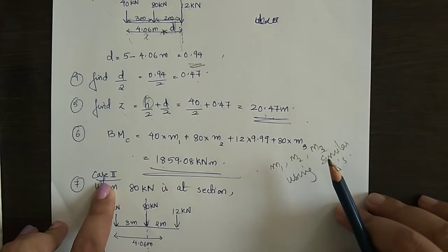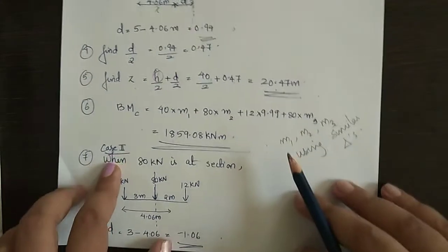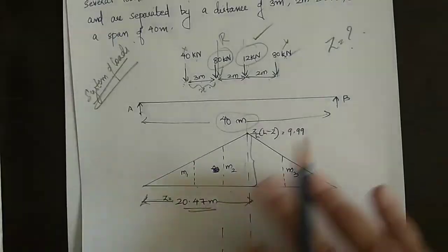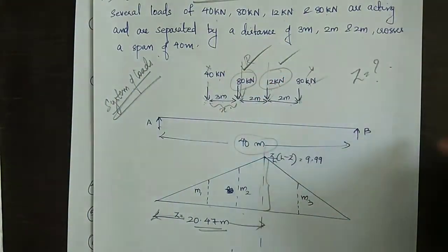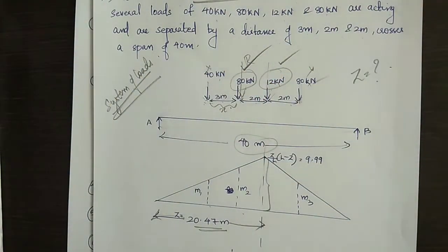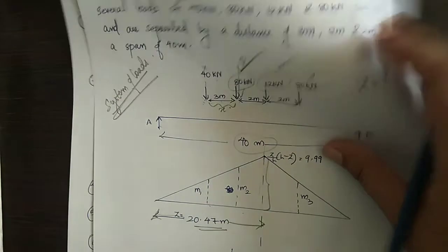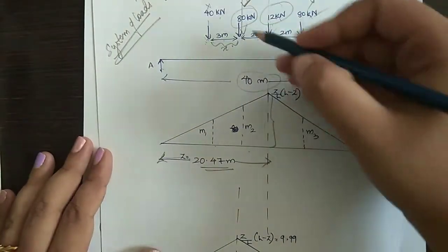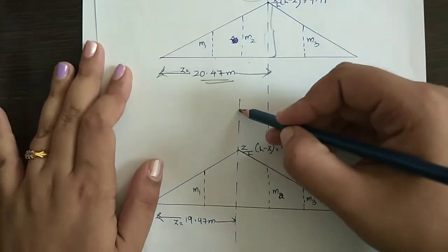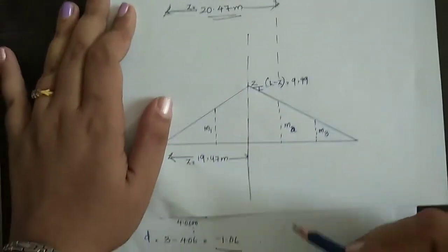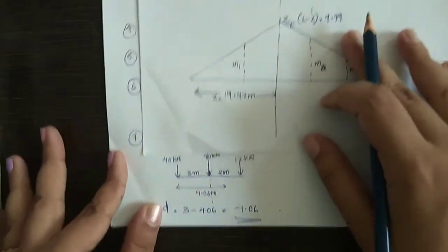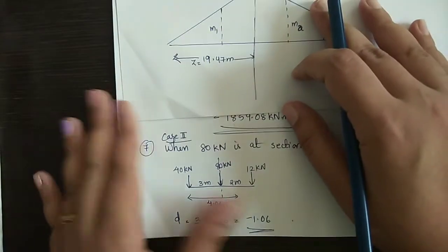Now we are placing the other load, 80 kilonewton at the section. That is, among the 2 loads considered, we are taking the other load. So we are going to draw the section along 80 kilonewton. Again draw the ILD for bending moment. Follow the same procedure.